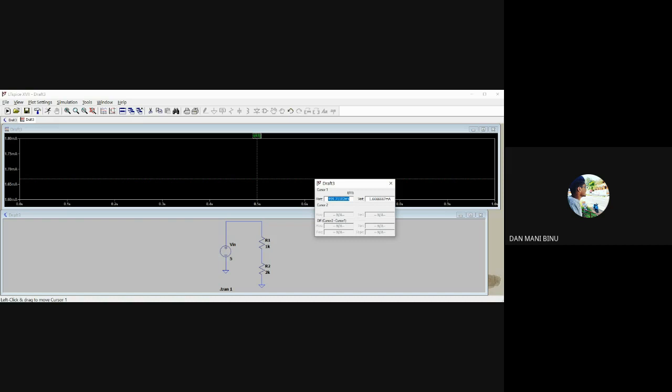Okay, so what does this show? Does it give the current shown in the middle, or does it show the maximum current? I think it shows the maximum current. I haven't tried it with this inductor circuit. To get the actual value, you can click here, and it shows the actual value. If it's a constant current, you can see the exact value. Otherwise, you can change the tick and the scale of the y-axis so that you get the exact value.